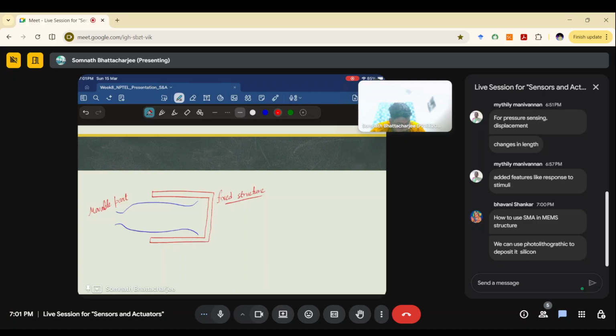And this is not a single strand, right? It is like this, and this is also like that as well. Based on the design, you can make it an accelerometer, you can make it a gyroscope and everything. To make this movable part completely movable and detached from the fixed structure, we can use springs. So based on the springs, they will be connected.